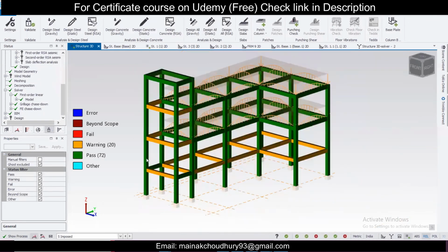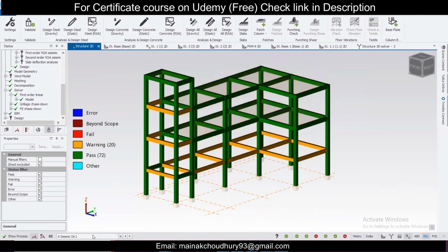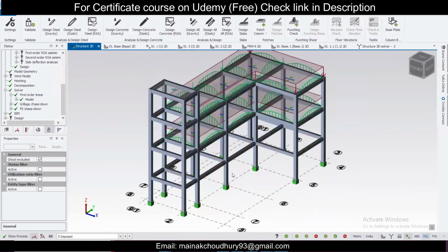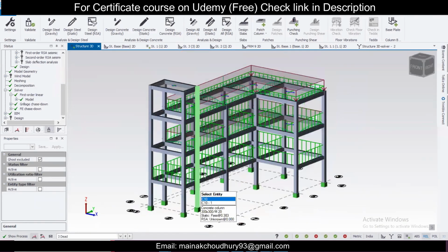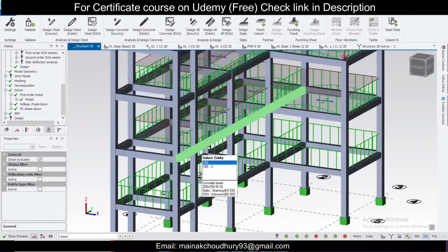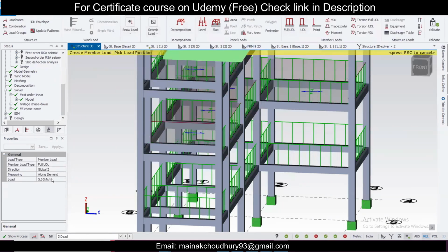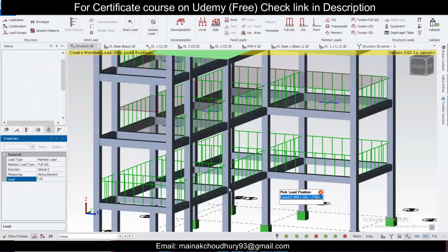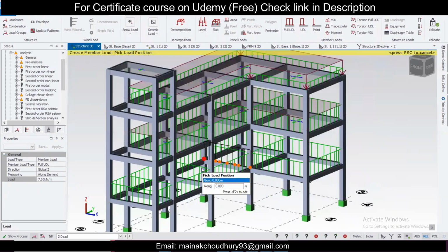Okay. So let's see, the loads are okay here. Dead load. Yeah, loads are okay. Live load. Yeah. So it is okay. Just click on escape and see the dead load, and this portion dead load is gone. So go to load, go to full UDL, click on 7, and I think this one I can apply here like this. Yeah, remaining is okay.